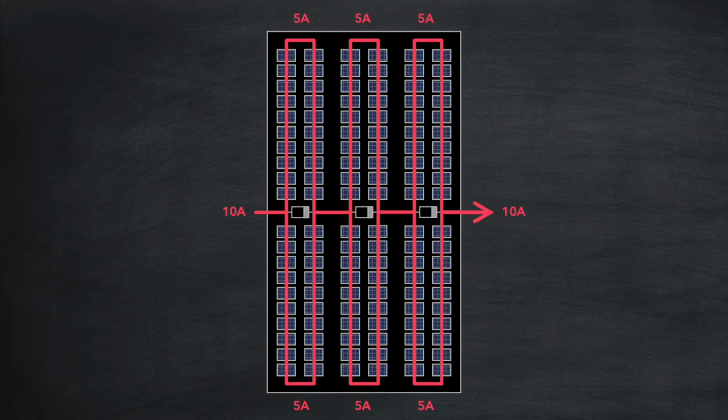Each half cell operates at 0.5 volts. The voltage is the same as it would be for a full cell, but now only has 5 amps flowing through it. So that's a generation of 2.5 watts per half cell. Each substring contains 20 half cells, so that gives us 50 watts generation per substring. As we have 6 substrings, that's a total generation of 300 watts for the panel, the same as we had for the standard panel.